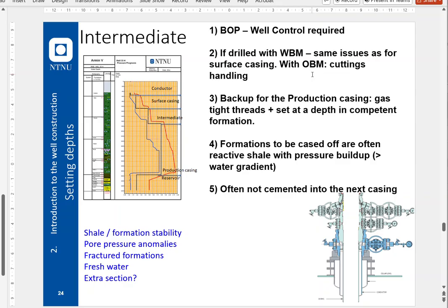This section is very important for wells that have gas lift as a feature. You may have to certify the intermediate casing as the same as the production casing, because you have a connection between the tubing and the production casing where you're injecting gas. Yeah, it's a part of the well integrity. It's just something to think about. Sometimes that impacts our casing design.